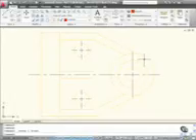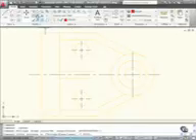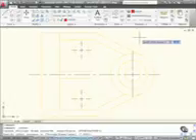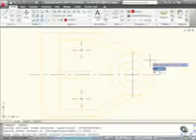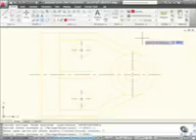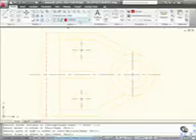Now there's a really lovely feature available to you in the offset command. If I go to offset again now, but before I specify any offset distance, I right click and go to layer, I can now select the offset objects to go on the current layer by selecting current there. You'll notice we've been using the source object up till now. Select current and now specify an offset distance of 5.25 and press enter. I'm now going to select this line here, move to the right and left click for the direction. It's put it on the current layer, the hidden layer there. So I press enter to finish.